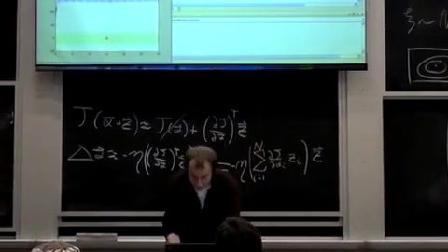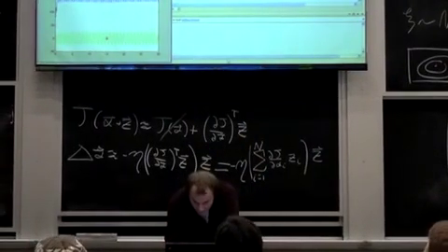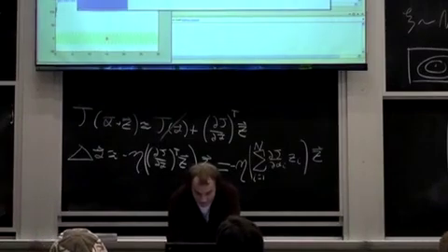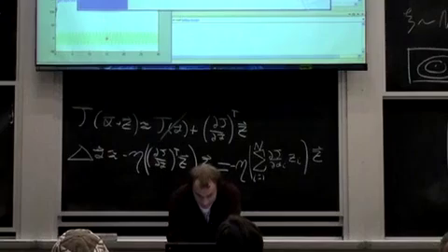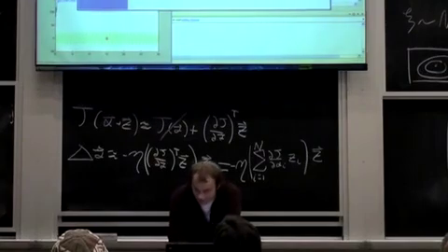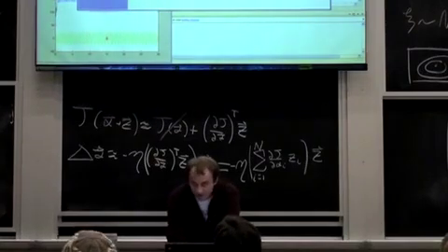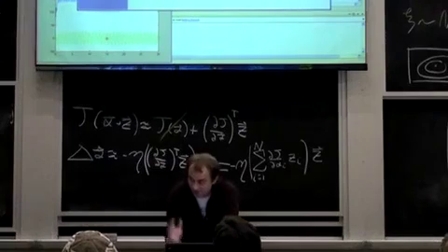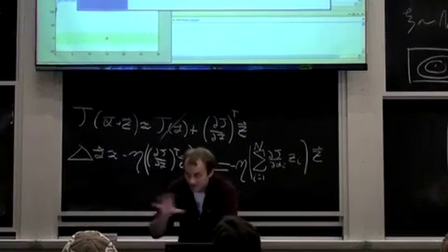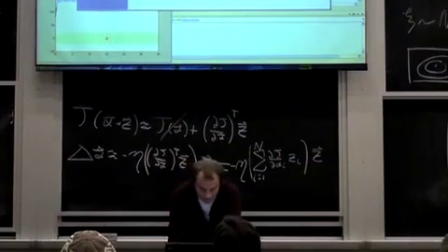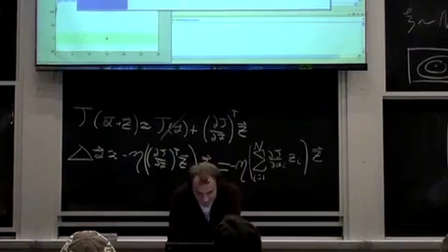Here, this is the sample system, and you can see how this is robust to really noisy systems in practice. Because when I ran it on the flapping thing down at NYU, consecutive evaluations could be very different, not because of any change in policy. You run the same policy, you get a big variance. That's just because you're running on this physical robot with this fluid system, and you're measuring the forces with an analog sensor, so it's very noisy. But it's robust to that, and that's what's so nice.